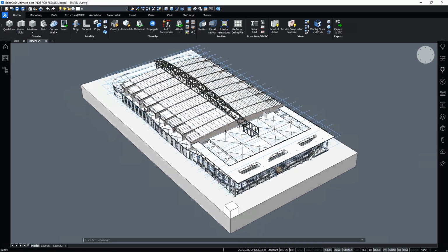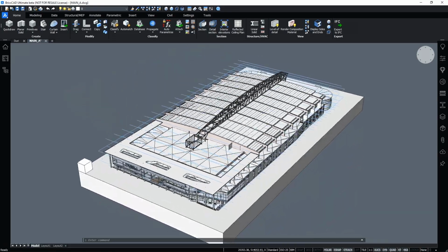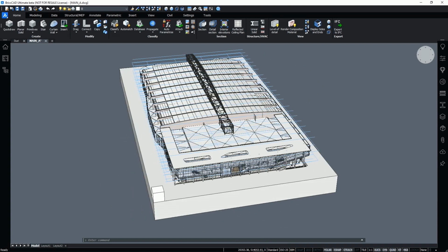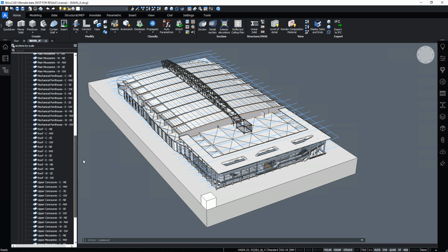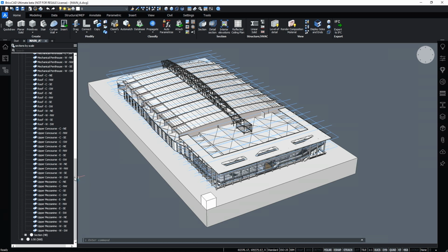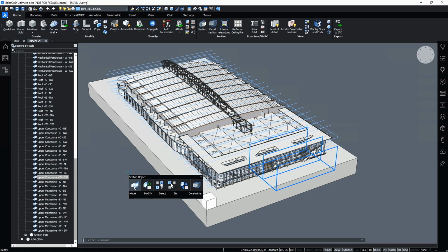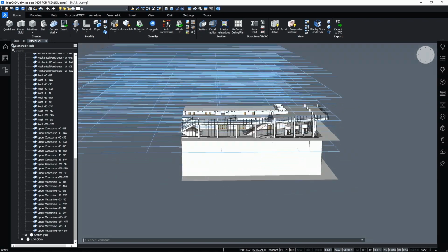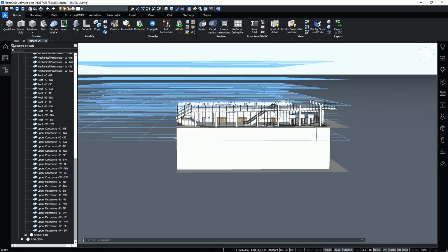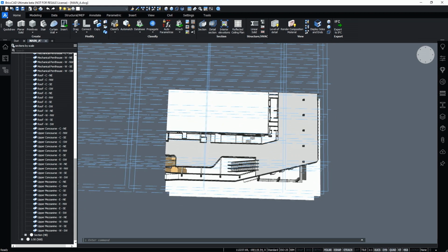So we start here from the master model of the Kentucky Convention Center. To generate the plans of this large building, section volumes were made that represent only a smaller portion of the model. These section volumes cut through different XREFs of the master and can be used both for checking the 3D model, but they are also the basis to generate the construction documents. Elevations and vertical sections were constructed in a similar manner, and as a result, the entire model contains more than 700 section volumes. Let's isolate one section volume that we will work on.